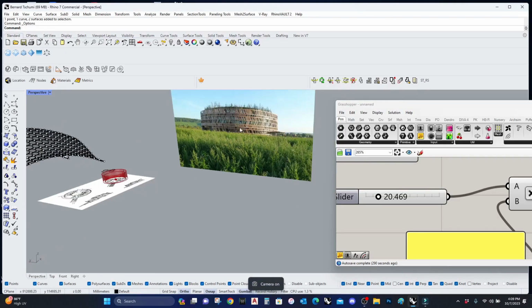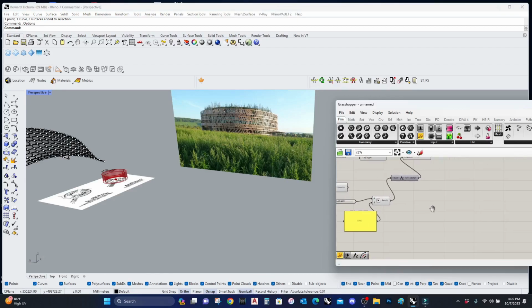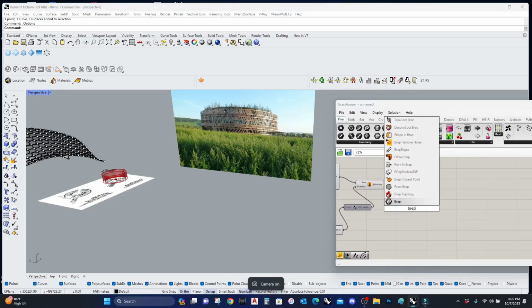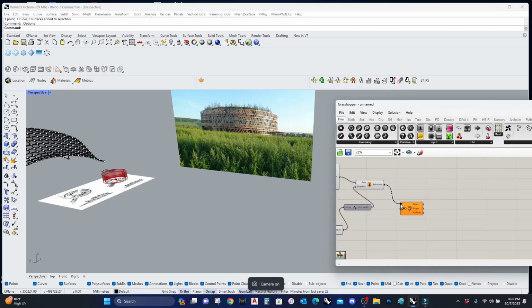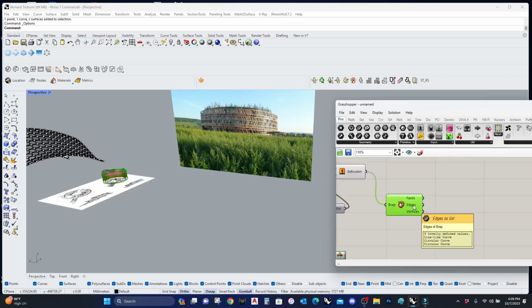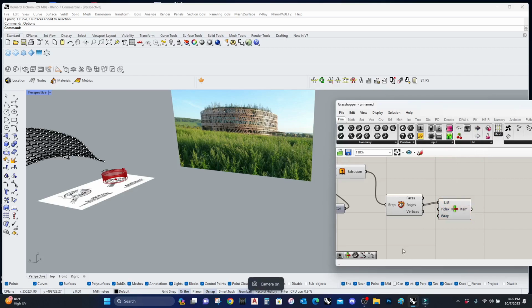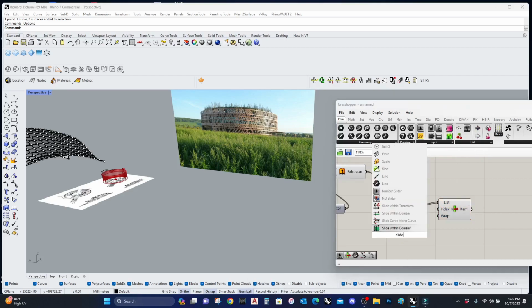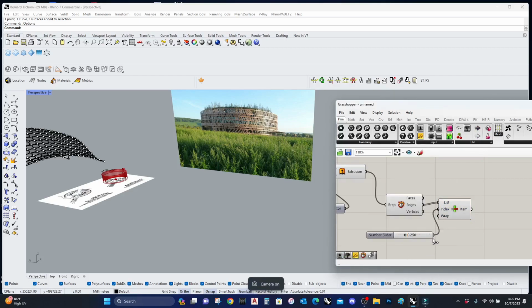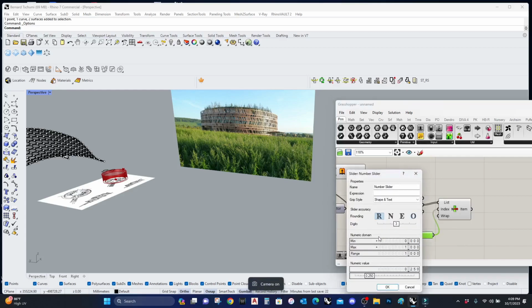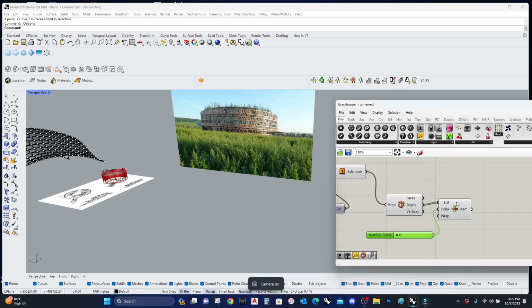So now we want to create this interesting spacing. So I am going to B-rep explode this item. I want to grab one of the edges. So I'm going to go to the list item, slider. There's 3 items, so as you know, I'll put 2 because everything starts on 0.